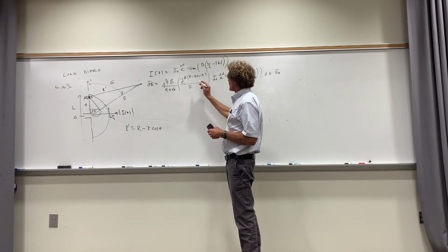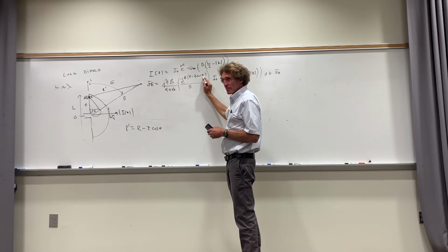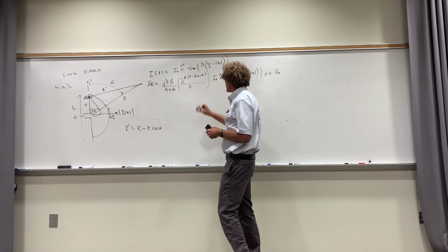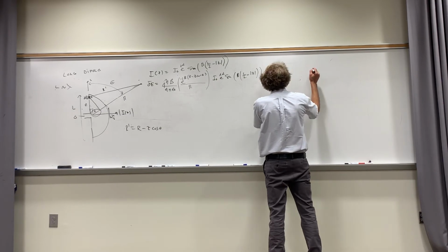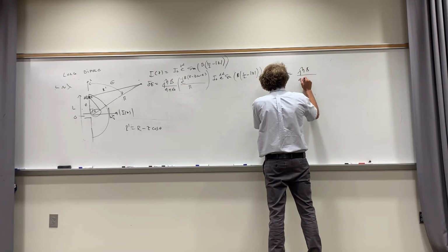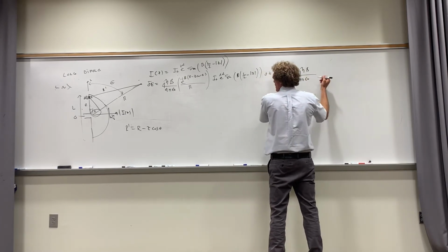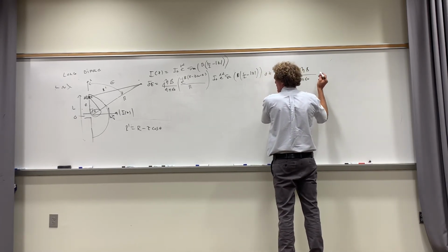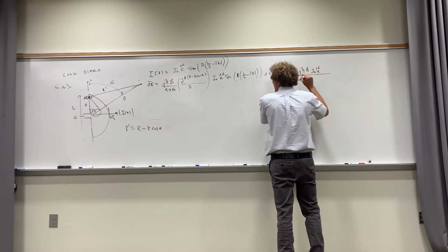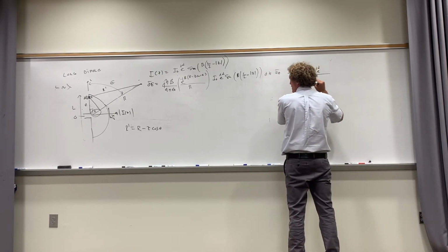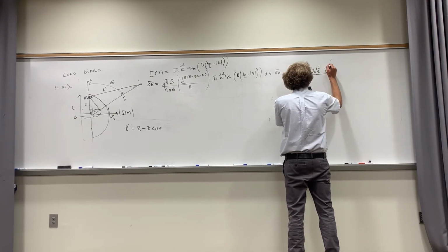Follow me? When I have an exponential, I can break it up into 2 exponentials. Do you agree? Let me do it right here for you. So now I'm going to take all the stuff that I'm not going to use out front, and I'll have j eta beta over 4 pi epsilon naught. Then I'm going to have I naught e to the j alpha, and then e to the minus j beta r over r.